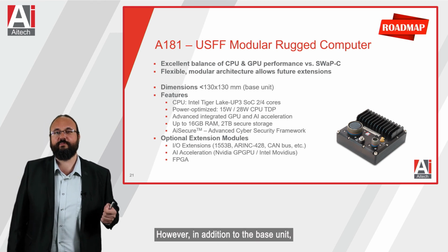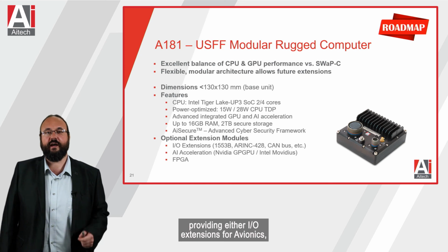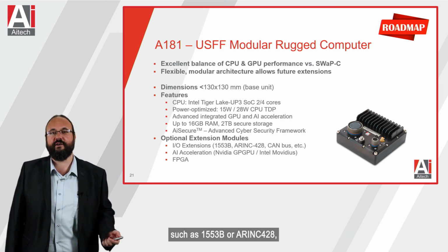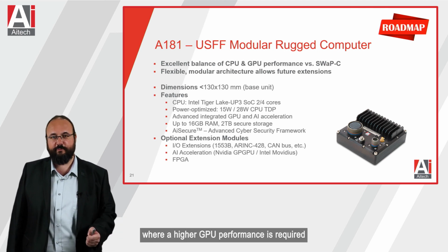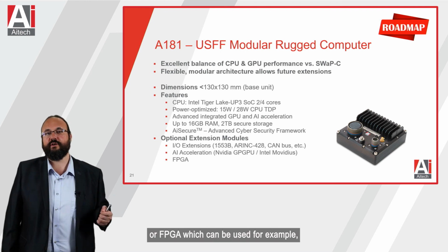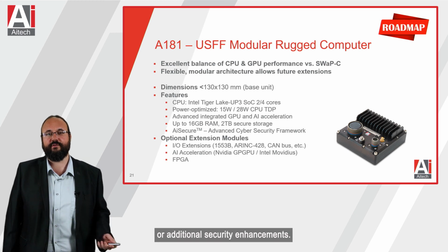However, in addition to the base unit, various extension modules will be available providing either I/O extensions for avionics, such as 1553B or ARINC 429, additional AI acceleration where higher GPU performance is required, or FPGA, which can be used for example for offloading of digital processing functions or additional security enhancements.